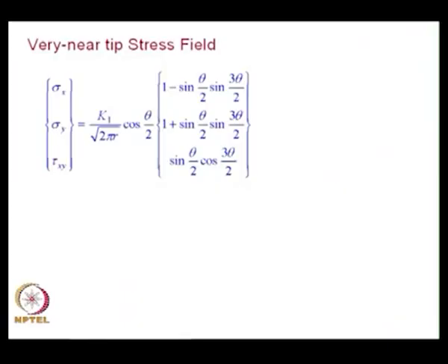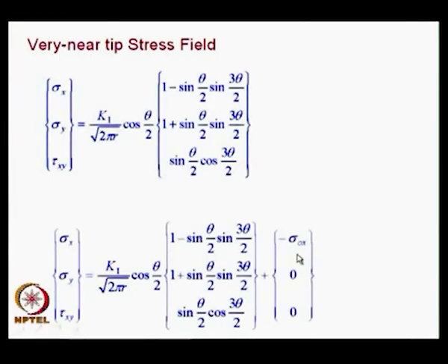They essentially go to 0. So, you are only capturing the stress field very close to the crack tip. And what was the modification done by Irwin? He simply added one extra term. And I had mentioned earlier that you need this to interpret the experimental fringe pattern.